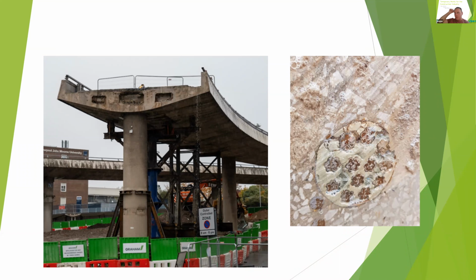You can see that the steel tendon has retracted slightly, just a little bit, but that's to be expected because it then has to re-anchor. And it's that same effect I was talking about earlier. If you stretch a piece of steel, its cross-sectional area reduces because it's got longer. And then as you release that tension, it swells or gets big again. It's Young's modulus. That's what dictates that behavior, the stress-strain relationship. It then expands and locks itself back into the grout matrix again, which allows it to re-anchor. So that section has still got the post-tension effects in place.